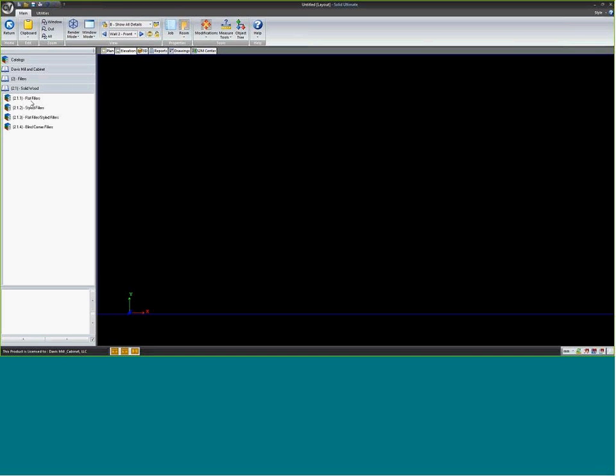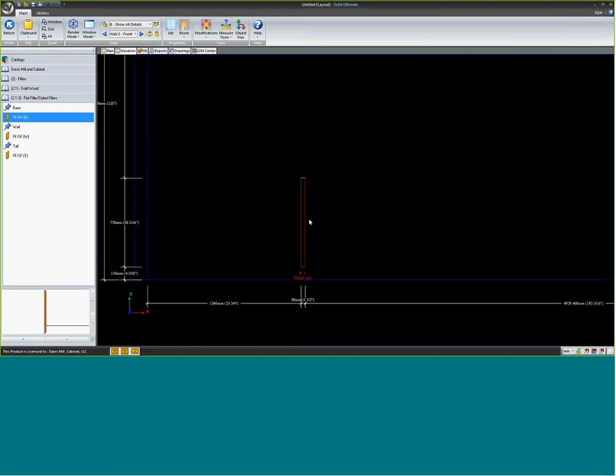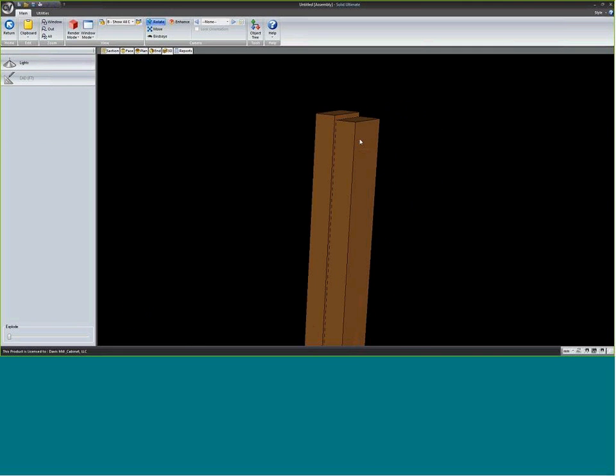Fillers, you've got a flat filler or styled filler. Most of the difference is your flat case depth filler versus a styled or overlay filler. You can drag them on independently as a single item, a flat filler by itself or a styled filler by itself, or you can drag on a flat filler, styled filler combo, and almost always this is what people use. So if I come in here, you've got 3 options, a base, a wall, and a tall. A base filler. If I go on the cabinet and look at it individually, you'll notice 2 parts in this cabinet. The first one is your styled filler, the back one is your flat filler.